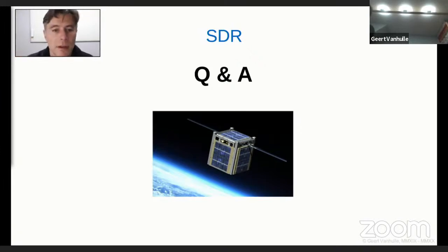That is of course almost unmissable when you move to applications in orbit. Now, one thing about the propagation delay, of course, that's why I was saying that there's a huge opportunity for people who are pursuing a PhD in chip design. It is to create FPGAs that are optimized for this. Now, having some of the blocks implemented physically already, because they are always being used, for example, these FIR filters, inside the same wafer of the FPGA inside the chip design.